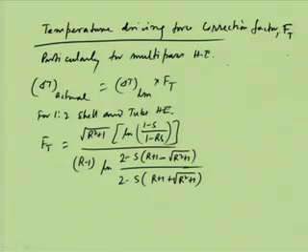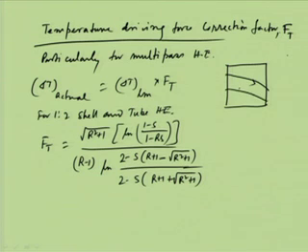I will say this now. The question is, what is S and what is R? If we consider a simple situation like this, this is the hot fluid and this is the cold fluid coming out. So, this is TH1, this is TC2, this is TH2 and this is TC1. The idea is that 1 means inlet and 2 means outlet, and TH1 and TC2 are the highest temperatures for the respective fluids, and TH2 and TC1 are the lower temperatures for the respective fluids.